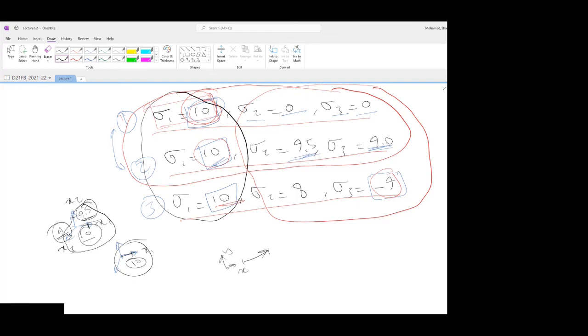But for the time being, I want you to understand the stress to be a bit of a complex phenomenon. It's not just a number. It's something more than a number. Now, these 3 numbers represent exactly the same phenomenon. If you look into the stress of these 3 numbers, they would probably look like this in 3 dimensions. So it is sigma 1,1, 1,2, 1,3, 2,1, 2,2, 2,3, 3,1, 3,2, and 3,3.